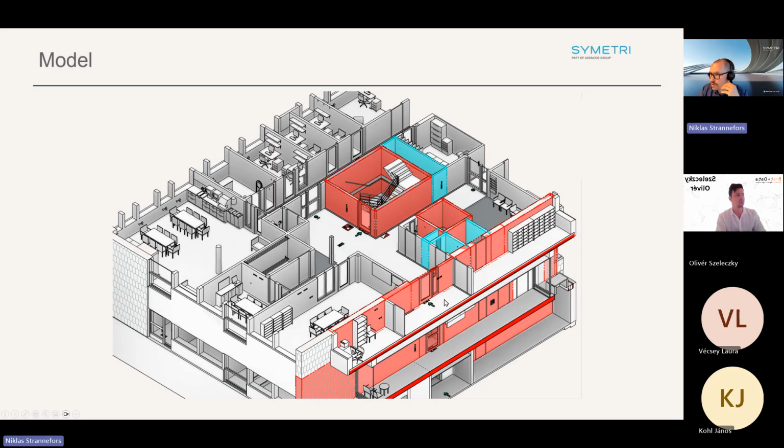You can easily do this in Revit. They're already prepared, all the families, so you can turn this on and off. By default, we have just slim. Basically, no one asked for this, but I like this more. Here I've just added more thickness on them. There's a parameter called NV width on type level. You can make them instance, but you can make them as thick as well. If you go to global parameters, I have one that controls everyone, if you want to make them all, say, 300 fast, and you would literally see them pop in 3D, especially with IFC.